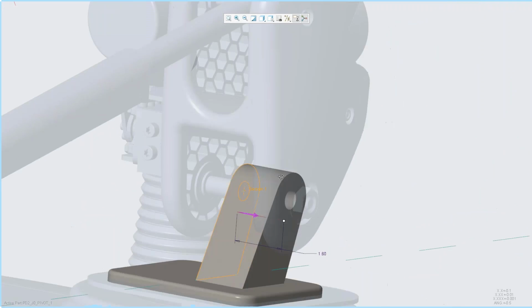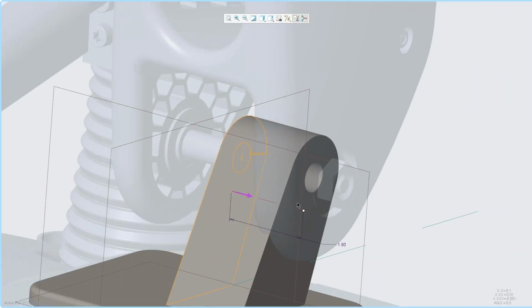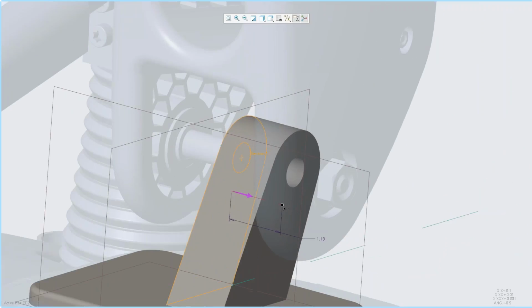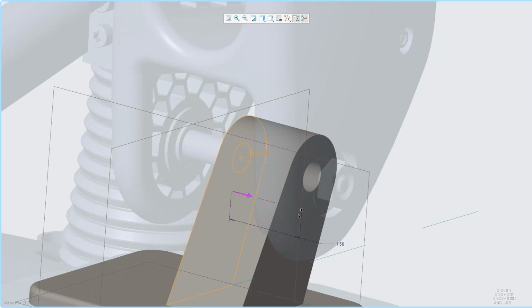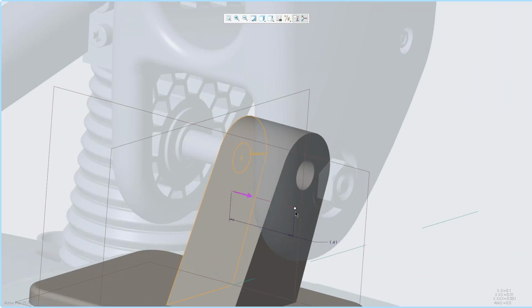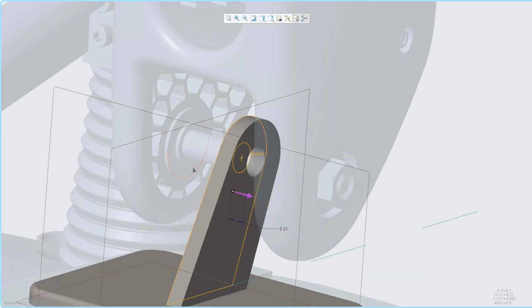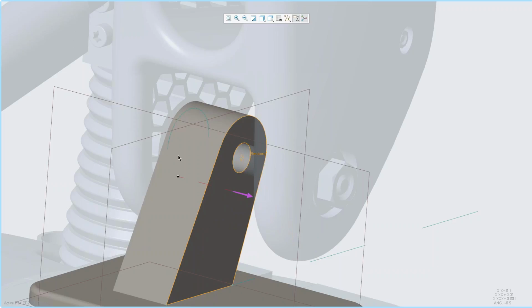Now this isn't new, but sometimes people aren't familiar with it. So we have this dynamic dragger, and I can select on the open square here, and I can drag my component as I want it. Now what I can also do is, as I'm dragging on this open square, if I hold down my shift key, I can actually say where I'd like that to go to. So I can say, come over here to this washer surface and snap that. So those are functionalities that we have, but that's a quick shift key to do that.